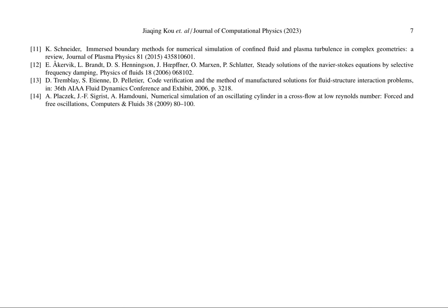Immersed boundary methods, on the other hand, enable the simulation of complex geometries by introducing a virtual boundary within the fluid domain. The key advantage of immersed boundary methods lies in their ability to decouple the fluid dynamics from the complex geometry, thereby simplifying the numerical implementation. This decoupling enables the use of structured grids, reducing computational costs and improving scalability. The authors discuss the various formulations of immersed boundary methods, including the continuous forcing approach, the discrete forcing approach, and